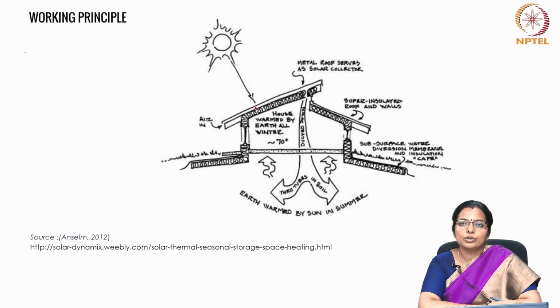The annualized geothermal solar system uses a separate solar collector to capture heat. The collected heat is delivered to a storage device such as soil or gravel or some hotbed or some such structure, sometimes even a water tank, which stores energy either passively by the convection of the heat transfer medium such as air or water, or actively by pumping. This method is usually implemented with a capacity designed for 6 months of heating.